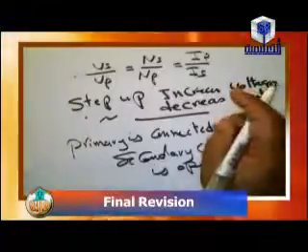The question again: if we connect the primary coil with AC voltage and the secondary coil circuit is open, we find that there is no energy consumed in this case, because the current passing through the primary coil will be opposed by a current against it according to self-induction or back EMF, which makes the current equal 0 in the primary coil. So the energy consumed in this case equals 0.